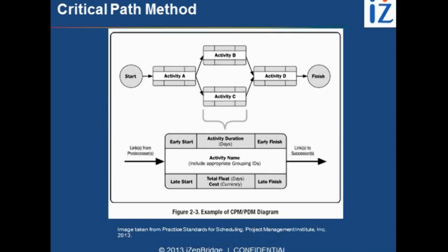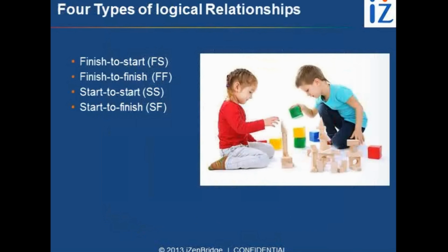Now in a critical path method, you identify various combinations of activities, and these activities will get performed in parallel. So some activity may run for a long duration, another parallel activity which is performed by another resource may get finished soon. So each activity is not of the same duration, and that is why the path which represents the longest duration is called the critical path, and the activities which are not following the critical path may have slack. So in order to identify slack, we work with late start and late finish dates. So let's move forward. Things will get clear as we get two, three, four more slides.